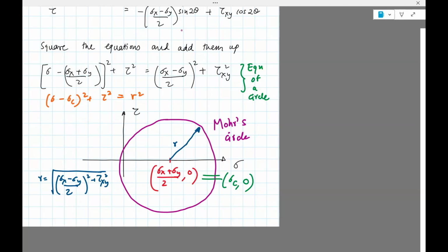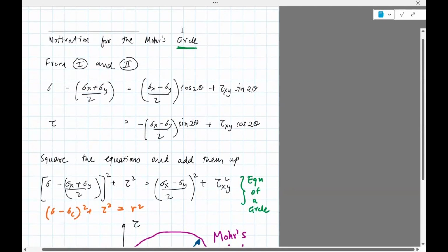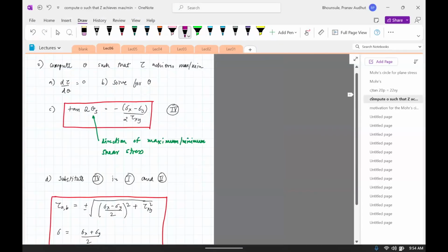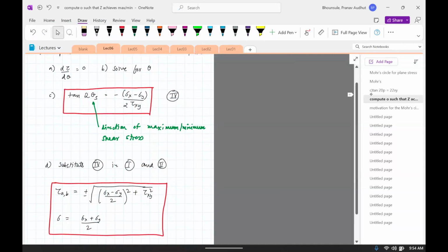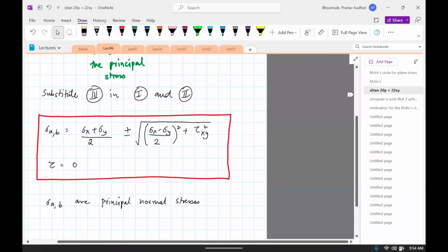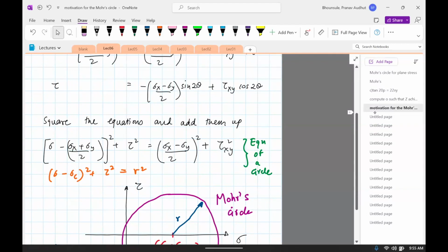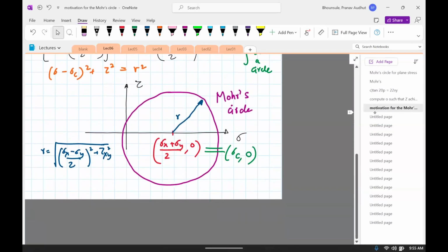So any problem in this section, you could do entirely based on the formulas if you're a formula person. By formulas, I mean, for example, the formula for principal stress. You could use these formulas, but you could also do the same thing entirely from Mohr's circle. If you're a visual person, maybe you do it from Mohr's circle. If you're a more formulaic person, you could use the equations. I'll do it both ways.